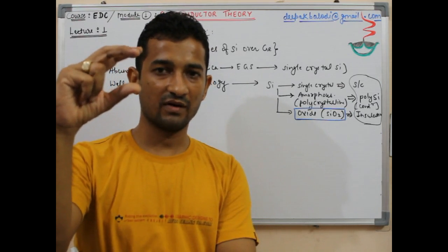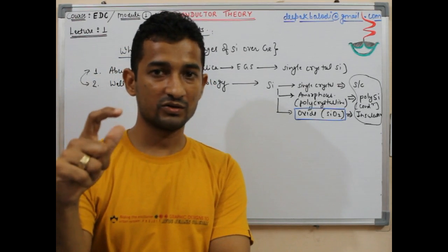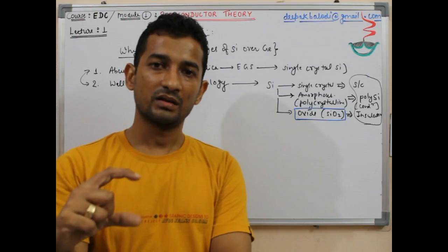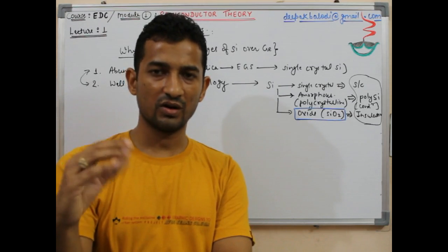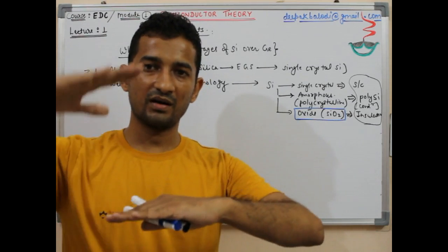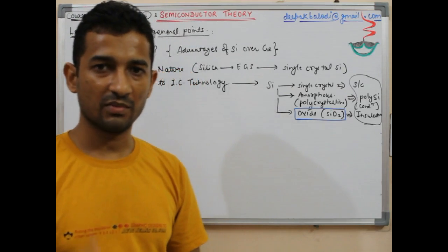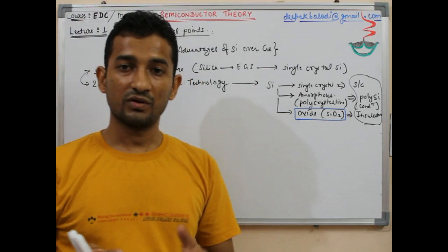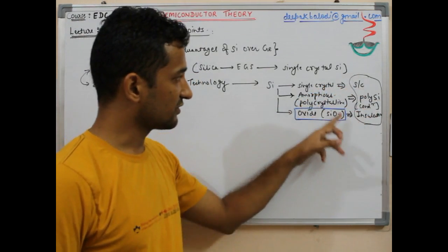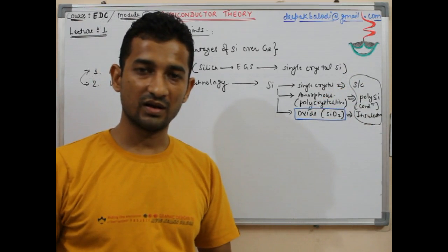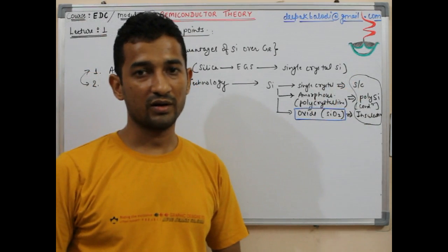Metal means we should have a very good conducting material, then below that we should have a very good insulating material or a dielectric material, then at the base end we should have a relatively better conductor than insulator, that is a semiconductor. So a semiconductor and metal, and in between there is a dielectric, so this makes a MOS structure, metal, oxide, semiconductor. So specifically for MOS or for FETs, this nature of silicon, that it has been found or it could be developed in all three formats, this property has been exploited to a great extent.